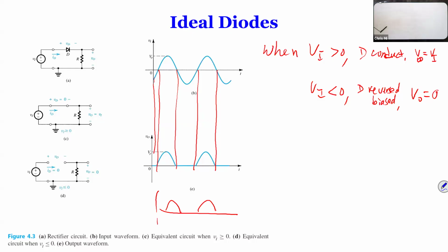I know in the past, students have sometimes made a mistake saying, "Oh, this is the actual circuit. I can do a loop analysis, and I found that the voltage here is the same as the voltage here," which is totally wrong because there's no current. Okay. Now, where did the voltage go? Well, if you measure the voltage over here, you see what you get? That's a negative VI. So the voltage, where did it go? It went to the diode. Because the diode does not conduct current, it has a voltage.